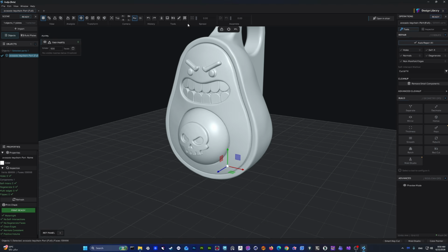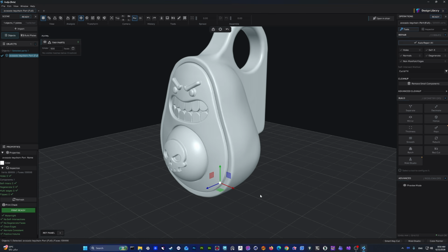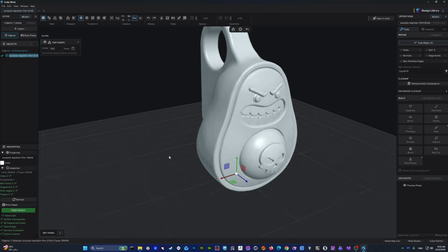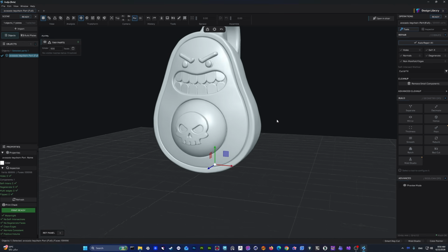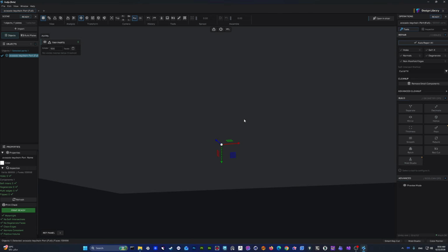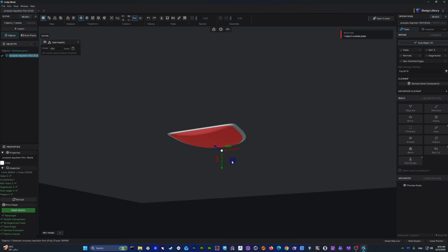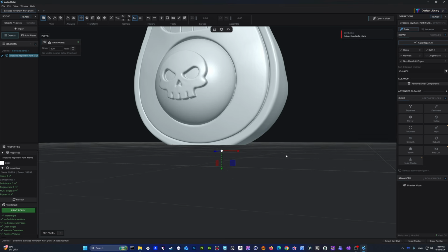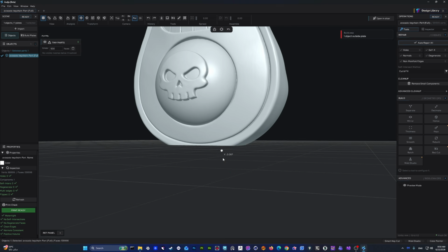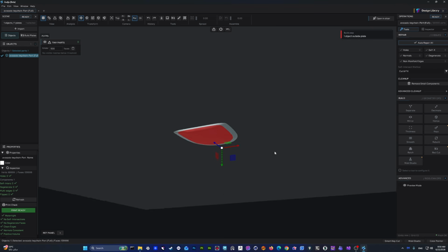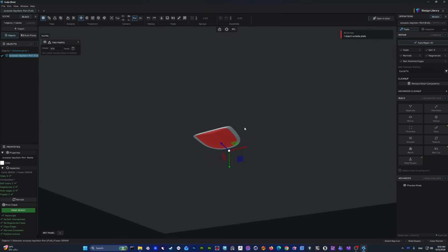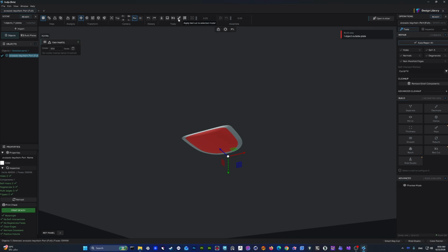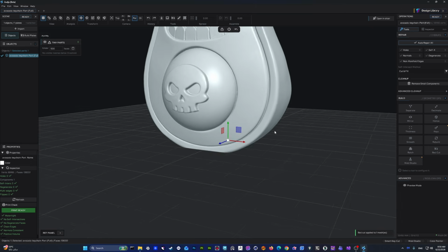And this one is for applying the cut under the plane or the plate of your model. So if you have a design that doesn't have a good first layer, you can just move the design down, as you can see, and I can see from below where the plane is going to cut, and I press apply, and that's it.